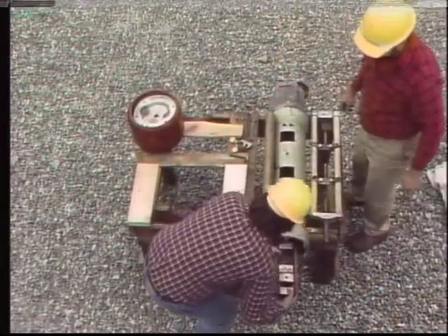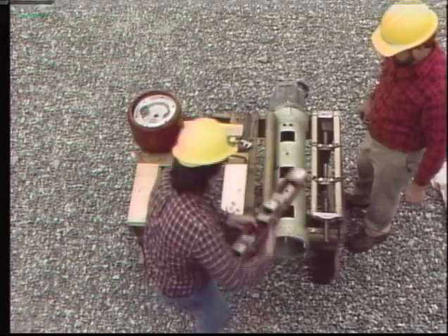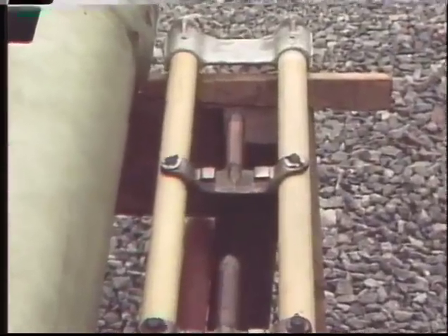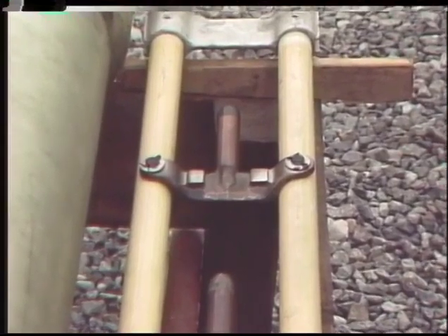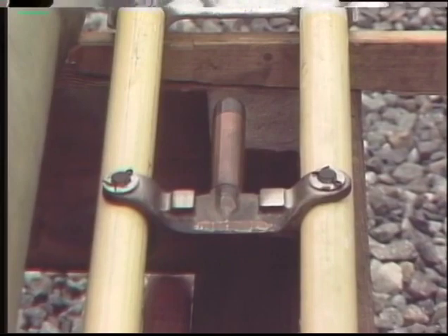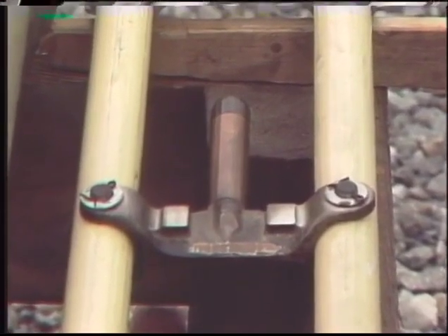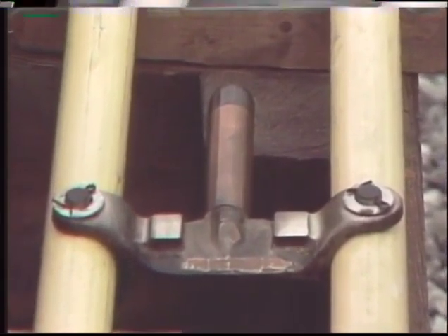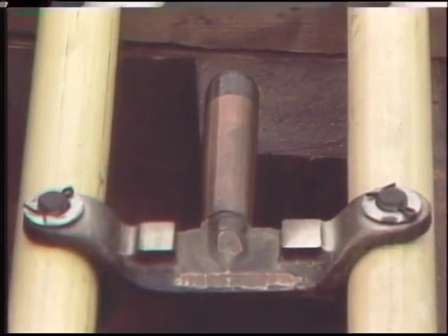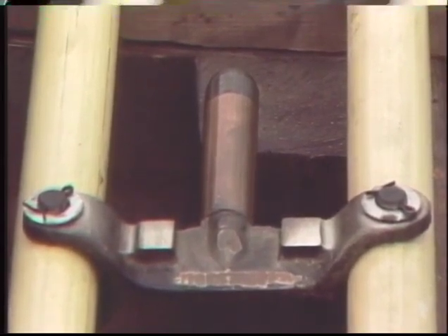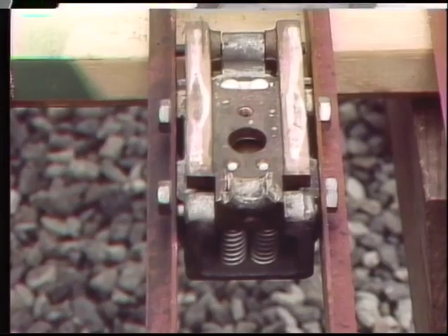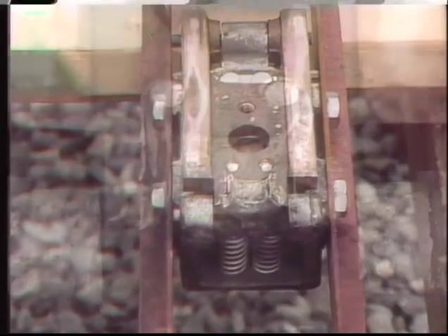The contacts are an especially important check in any breaker inspection. There should be very little wrong with the main contacts, since it's the arcing contacts that break the circuit and are subject to arcing. If main contacts are burned, pitted, or charred, they may not be separating before the arcing contacts. Damaged main contacts may need to be replaced, and the open and close sequence of the contacts may have to be checked. You can expect arcing contacts to be discolored and pitted.